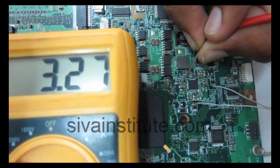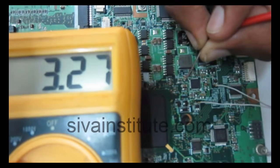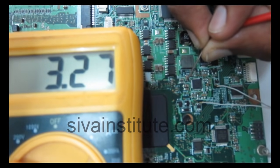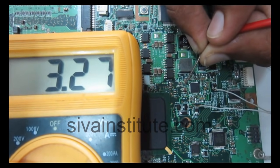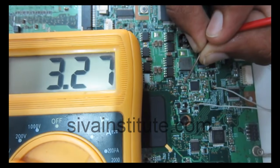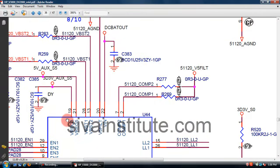When you first connect the adapter or battery, you should check here at the 5 volts and 3.3 volts regulator IC. This is the 5 volts and 3.3 volts regulator IC. Whether this is OK or not, you should check here. In some circuits, there is no 3.3 volts output from this chip. How to find out that circuit, I will explain here. Only a 5 volts regulator gives 5 volts output from this IC, but the SIO chip wants 3.3 volts DC. I will explain that circuit.